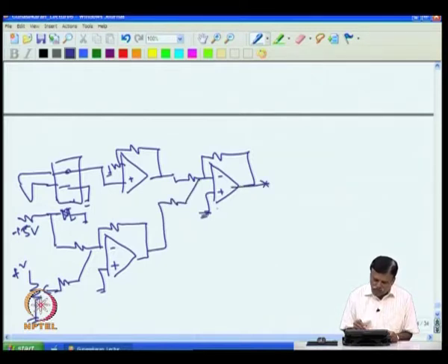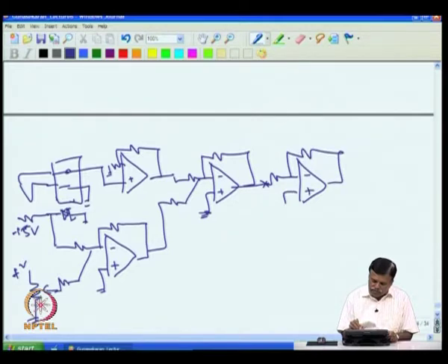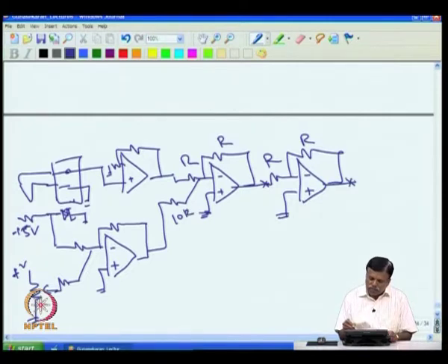Of course, this is going to the minus side. If we want to make it plus, we can invert it, but I think we will not do that. We can simply invert it to get positive voltage. That would be easier for discussion, but there is nothing wrong in negative voltage. We can work with negative logic also, but for a beginner it confuses. So I made it such that the gain is here 1, and here you have R, and R we got a 10 R. So at this point you will get voltage corresponding to temperature.